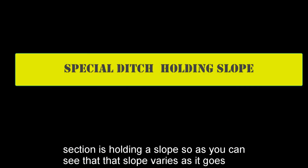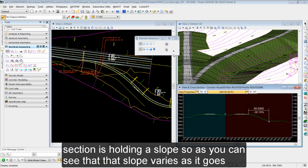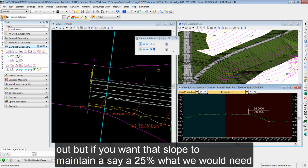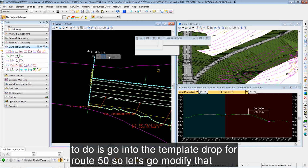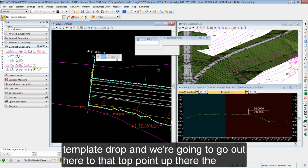Now this next section is holding a slope. As you can see, that slope varies as it goes out, but if you want that slope to maintain, say, a 25%, what we would need to do is go into the template drop for Route 50. So let's go modify that template drop, which is the second tool in the heads-up display for your template drop.